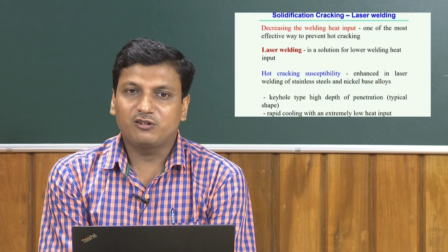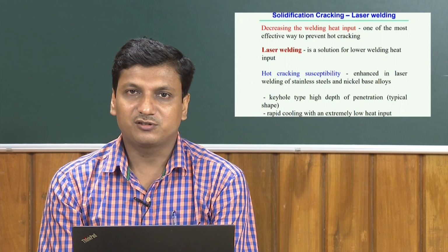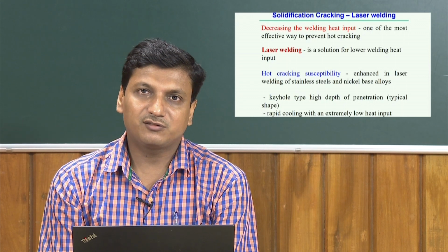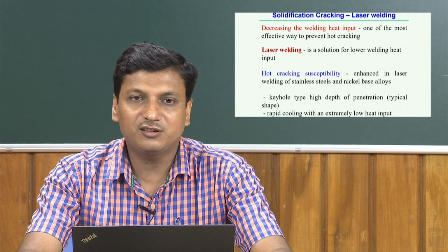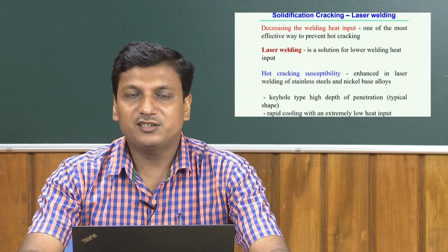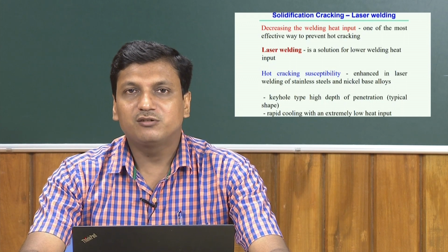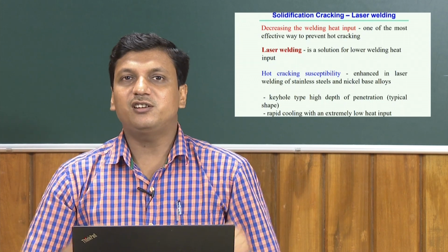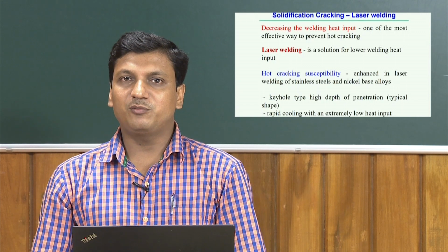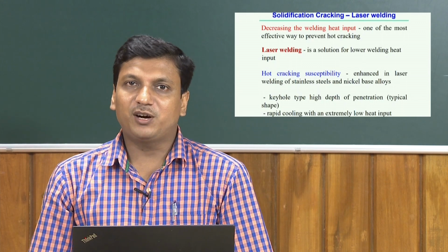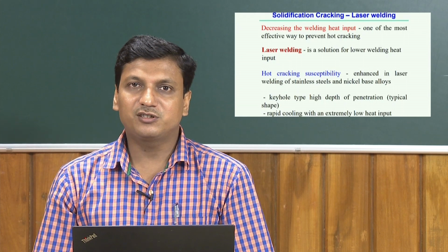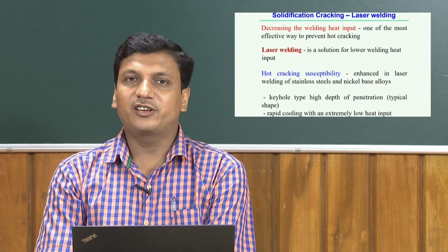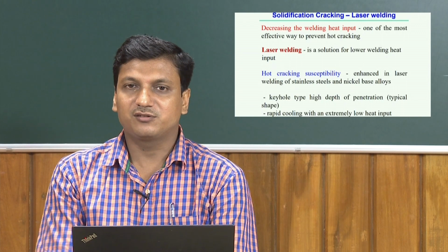The typical shape of this also promotes solidification cracking or hot cracking phenomena in the laser welding process, if we do not take any precaution. Normally there is very rapid cooling, but even at very low heat input, that sometimes promotes the hot cracking phenomena in laser welding processes.